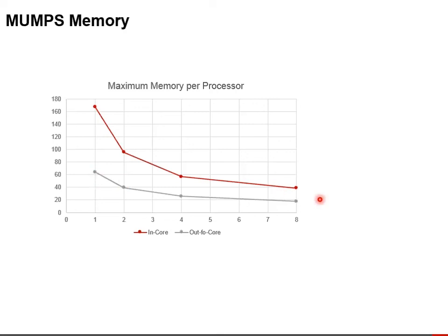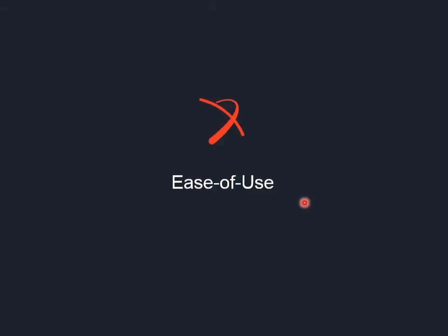But when we use parallelization, DDM, and the distributed assembly, each one of those machines can be as little as 20 gigabytes to run that particular job. So we don't need a large amount of memory on a given particular machine.